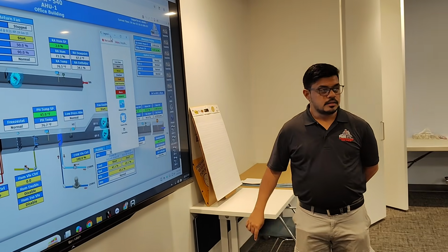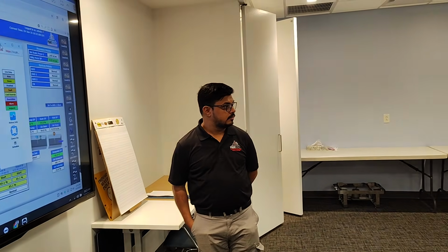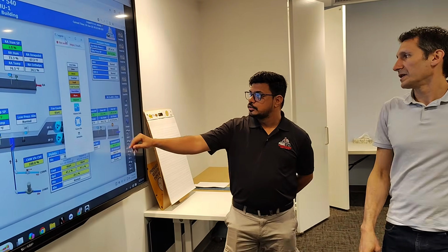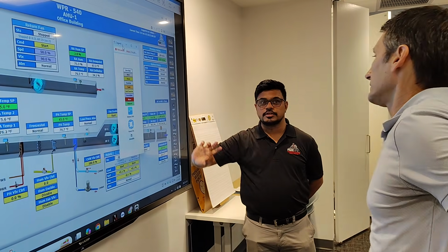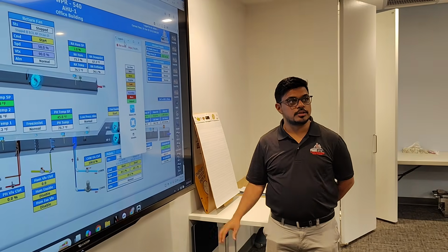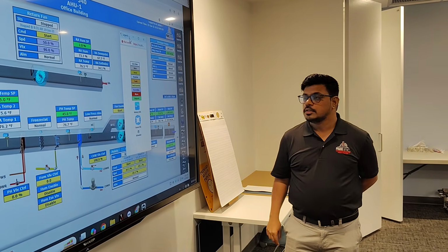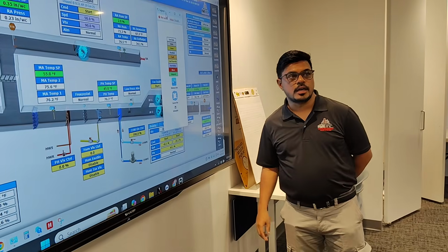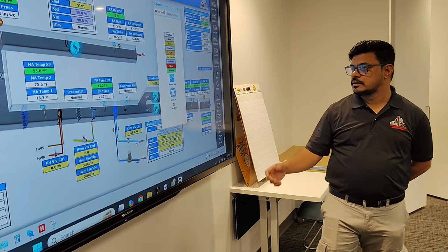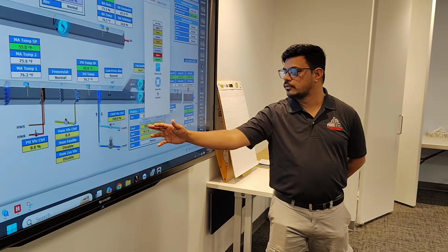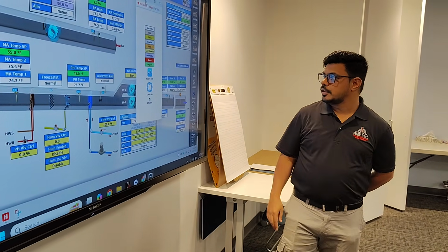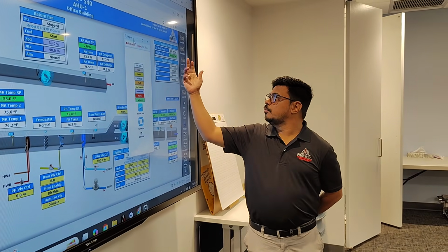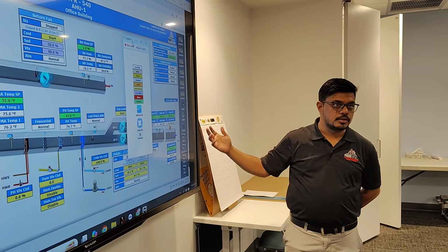And look, he's got that window open that explains the colors. That's why I was coming up here on the legend. So the green ones are your set points, which you can set according to the value you want. And then the yellow ones are your command override, the ones which you can override, like the chilled water valve, the fan command, the speed. Apart from that, the whites are your monitoring points or the lab data.